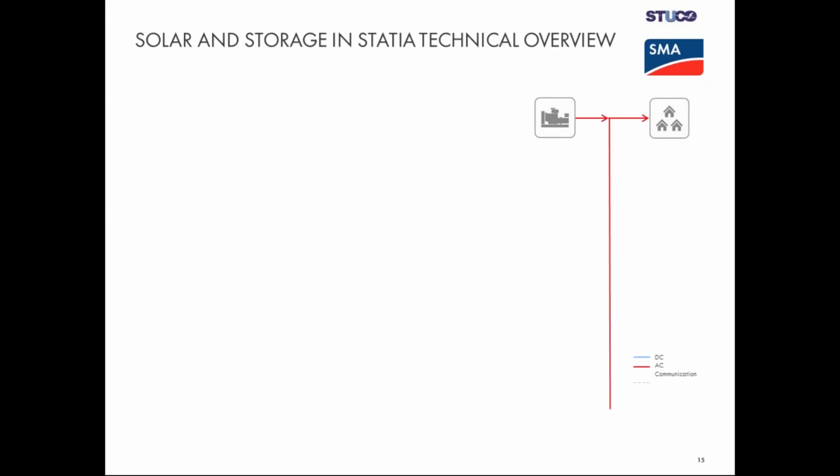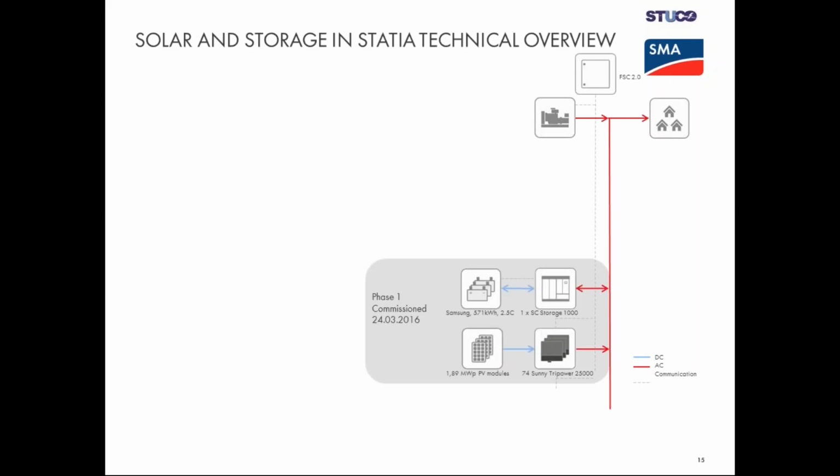Since then, we are looking at it, and I want to show you, perhaps first the system again. I keep it short, as Fred has presented it before. So, sorry for this, it's an oversimplified single line diagram, high level, and this is what we found when we entered the island: a generator fleet, a grid, and loads. So in the first phase, we integrated a 1.9 megawatt peak solar system with a 600 kilowatt hour battery system, basically to compensate the PV ramps. And we even got an award for it. I said it was new at that time in 2016.